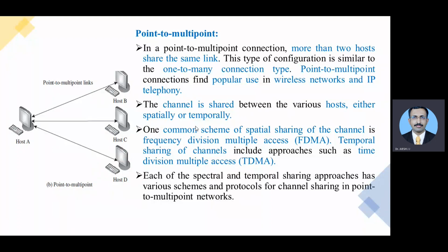Means you divide the frequency. In frequency division multiple access, you have certain frequencies. You split the frequency, and each slot is used as a different channel. In time division multiple access, you divide the time slots and use those slots for different transmission of information.